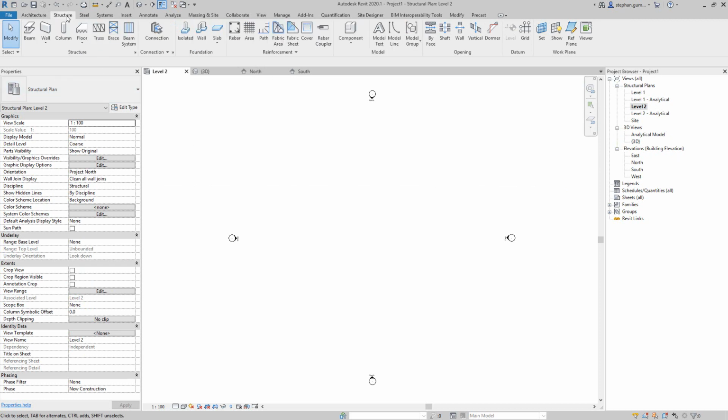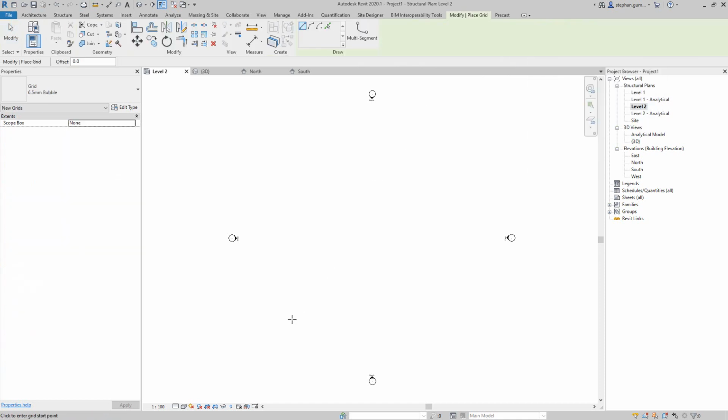Myself being a structural draftsman, I'm going to come in here and look at placing some grids, and you can see I'll place my first grid in this location. Now, by default, when I go to create my next grid, the system automatically gives me a suggestive difference and an intersection, a little bit like object tracking, so that I know exactly where I'm going to place my grid. If I pick here, I know it's exactly 10 meters, I know it's 90 degrees, and when I go near that other endpoint, it's now linked together. And you can see the elements are all controlled together.